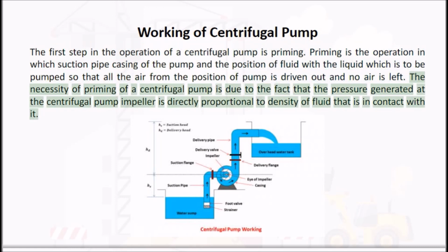The necessity of priming of a centrifugal pump is due to the fact that the pressure generated at the centrifugal pump impeller is directly proportional to the density of the fluid that is in contact with it.